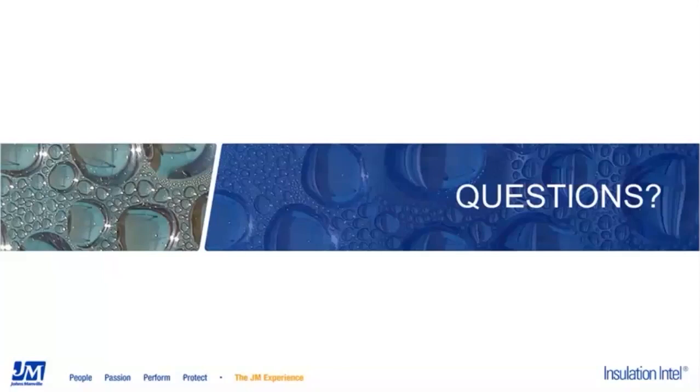This next question I'm also going to send to you, Jim, and that is, can I use Saran X around fiberglass over the ASJ jacket? Yes. Short answer is yes. Before you did that, I would question why you wanted to do it. You would not do it for appearance purposes. ASJ is going to look better than Saran X. Saran X is not the most aesthetically pleasing vapor retarder in the world. It often has some wrinkles and things in it. So I don't think you'd do it for aesthetics.